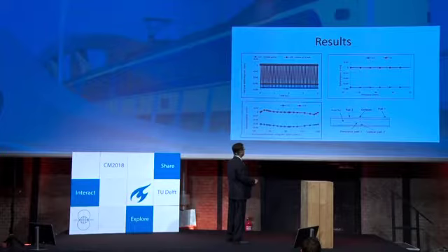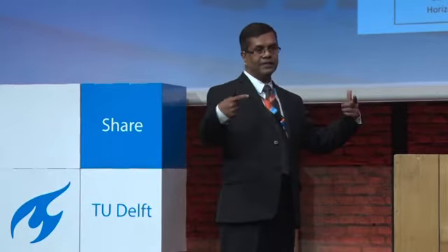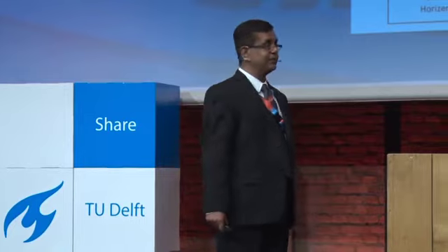If we see what is happening from top to bottom, you can see it is nearly this value, and it is similar all the way from here to here. What is happening to U3? U3 is longitudinal. You can see U3 from here to here is nearly 0. What does it mean? That means this is the neutral axis, and it is not deformed.